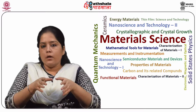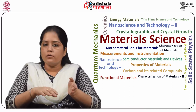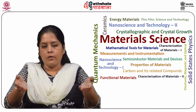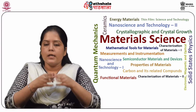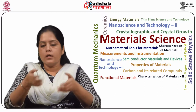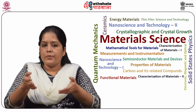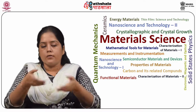So the aluminium alloys find extreme importance in both common use as well as specialized uses like car engines, car body, aircraft body, etc. There are different variants of aluminium alloys depending on the nature of preparation, cast or wrought, the kind of alloying elements, copper, zinc, manganese, silicon, etc., or the type of heat treatments T1, T2, T3, T4, etc.